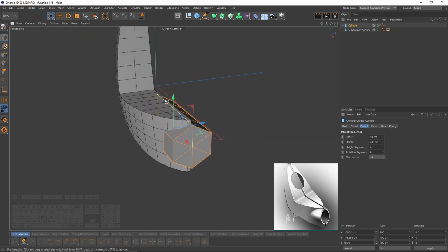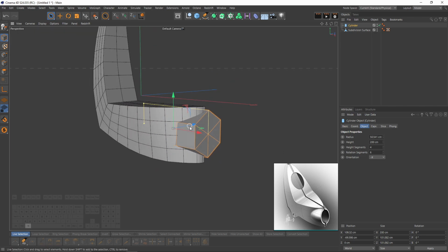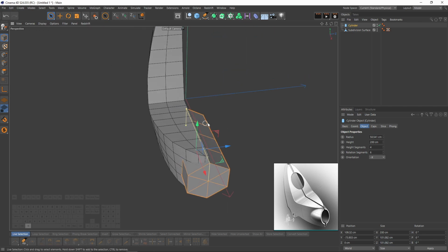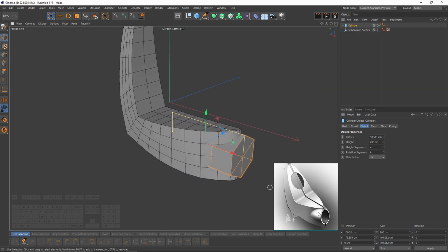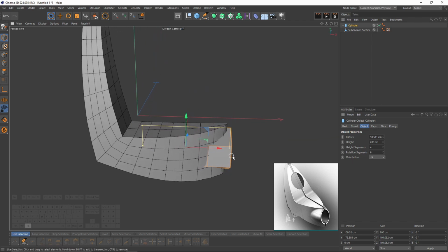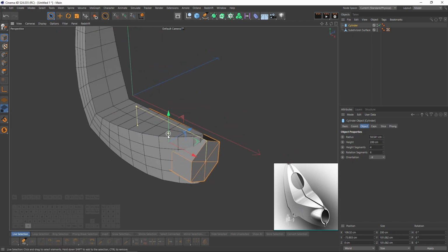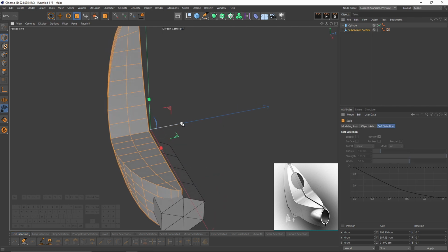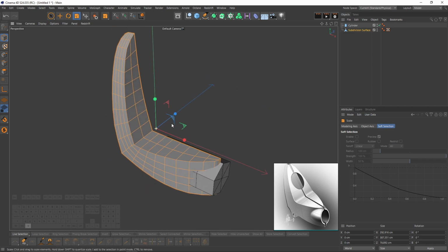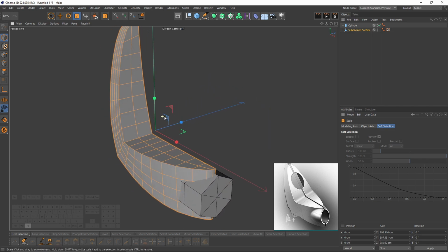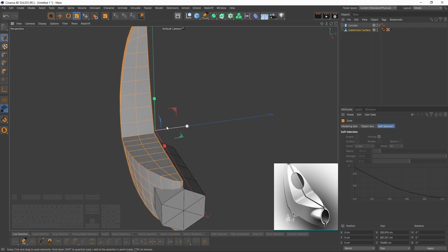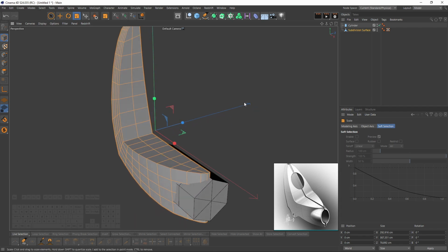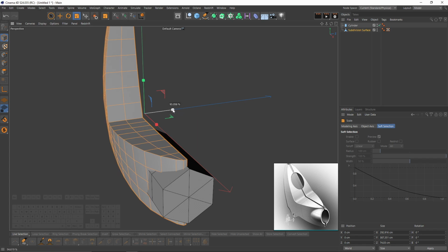Okay, not bad. Maybe we can scale it slightly. It looks like in my reference I have more space for the cylinder, but not in that case, because this piece is too curved. I mean, it has too much depth. So let's switch to scale mode and scale this like that. Since my origin will be right in the center in the vert coordinates, I can scale them easily.